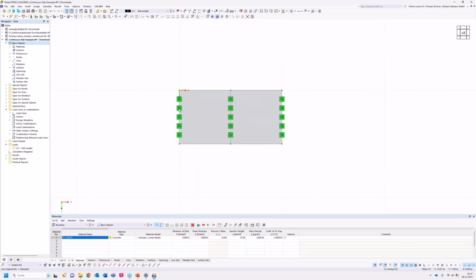This was in the presentation, I think about step 4, where we block some degrees of freedom. So we strike out some equations from the K matrix, and we also strike some degrees of freedom in the U vector. So now we have the K matrix ready. We also modified it with boundary conditions, and we have the U vector also modified, though it's unknown until after the calculation.